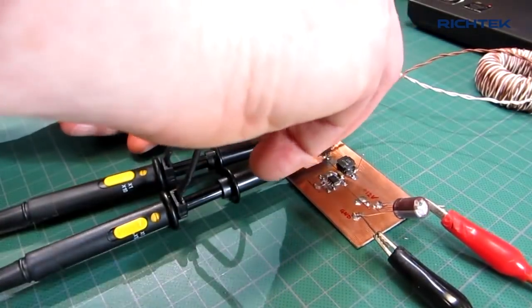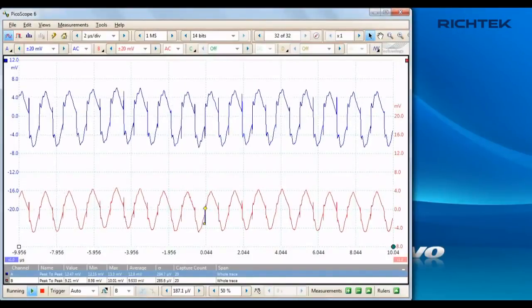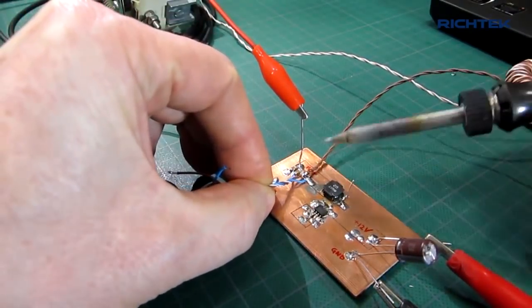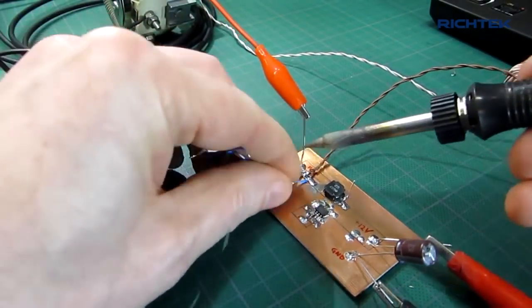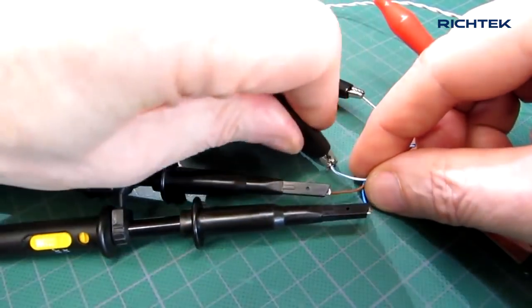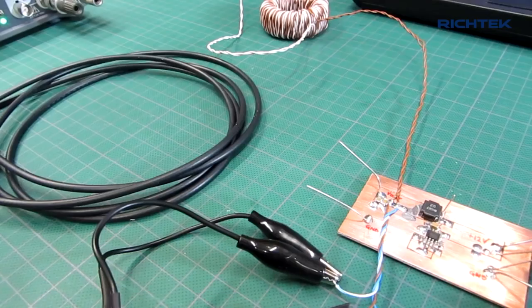Don't connect the probes with long ground wires directly to the measurement points. The inductor stray field will couple noise into the probe loops. It is better to bring the measurement points and ground away from the inductor via 3 wires twisted together and connect the probes here, which reduces noise pickup.